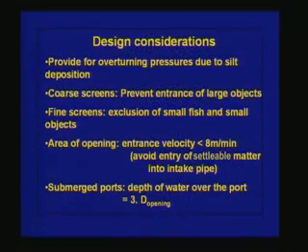The other important point is the overturning pressure due to silt deposition. Whenever we have an intake structure, it is creating an obstruction to the flow. This is particularly important when the intake structure is located within the river or within the canal itself. On one side of this intake structure there could be sand and silt deposition, and on the other side there could be scour.